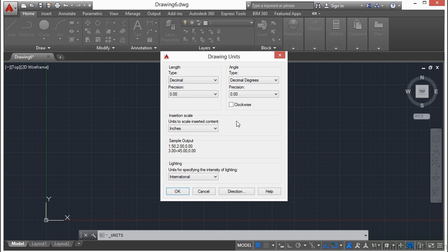It'll say it is 12 feet, 0.0000 inches, or whatever that case may be. One of the problems that you have to deal with in AutoCAD is that it is way too precise for a lot of our applications. You can draw much more precisely in AutoCAD than you could ever build for a lot of different things. So keep that in mind: just because you can draw something in AutoCAD, that doesn't mean that it can be built that way.